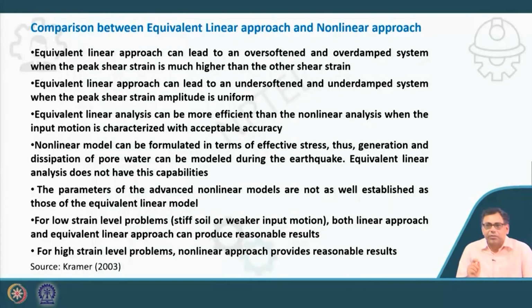In the case of the equivalent linear model, you have to generate the shear modulus degradation curve and damping ratio curve along with strain, and from there you will get the shear modulus and damping ratio at different strain levels. Then by the iteration method, you will get the shear strain, shear stress, all the values. Similarly, for the non-linear model, I have discussed how you will get the shear strain and shear stress at any depth along with different time.